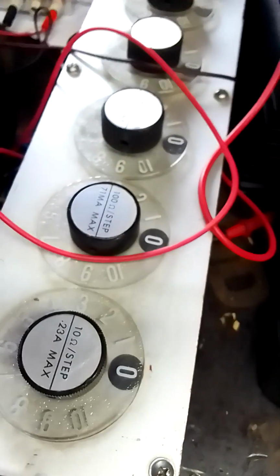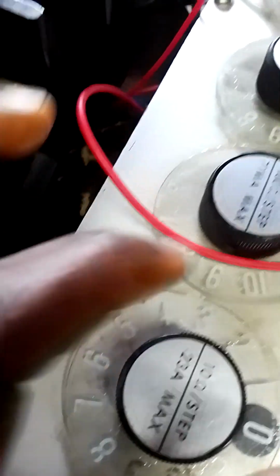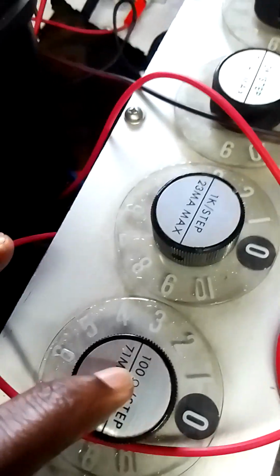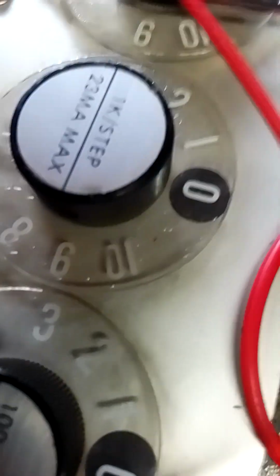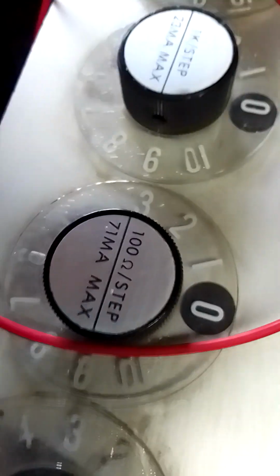So this is our resistance box. This value is from 0 here to 10 ohms. 0 to 10 ohms, you can see it. If you want to make your resistance go to 100 ohms, we have 1 kilo ohms, 10 kilo ohms, 100 kilo ohms, 1 mega ohms steps. So for all these mega ohms, we have a switch.